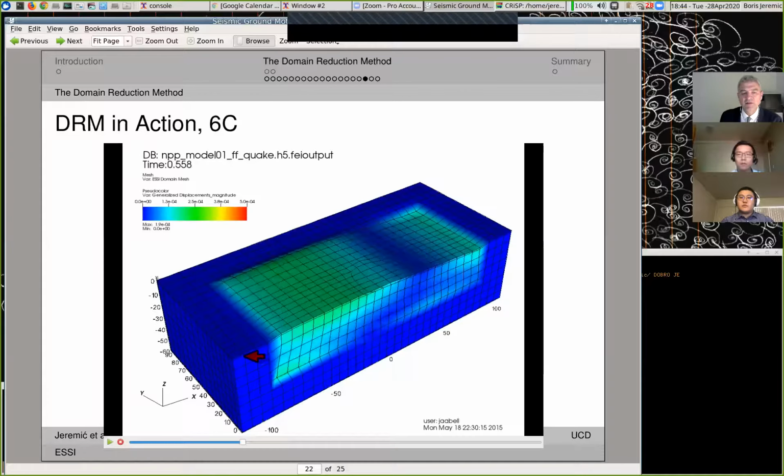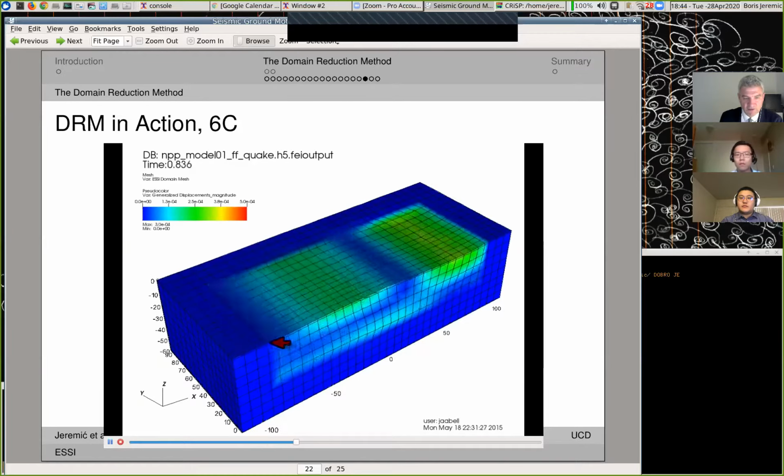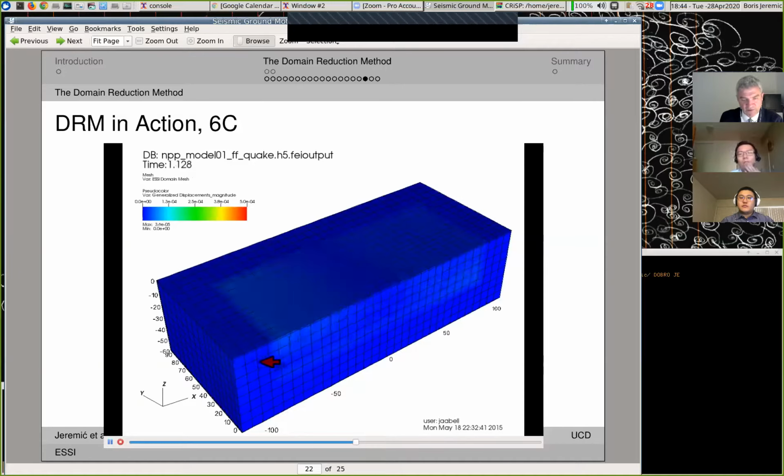In fact, a long time ago, one thing that you learn about finite elements is that you should always put enough boundary conditions to prevent rigid body modes. We played with this some 15, 16, 17 years ago, and we actually removed all the boundaries. And if you have a proper solver, you can have a model with no boundary conditions at all. You have to do pivoting. You have to be very careful about how you solve the system of equations. And the whole system was essentially just floating in the air. Nothing was coming out. So please observe how these waves are input inside through this one layer of elements, and nothing comes out.